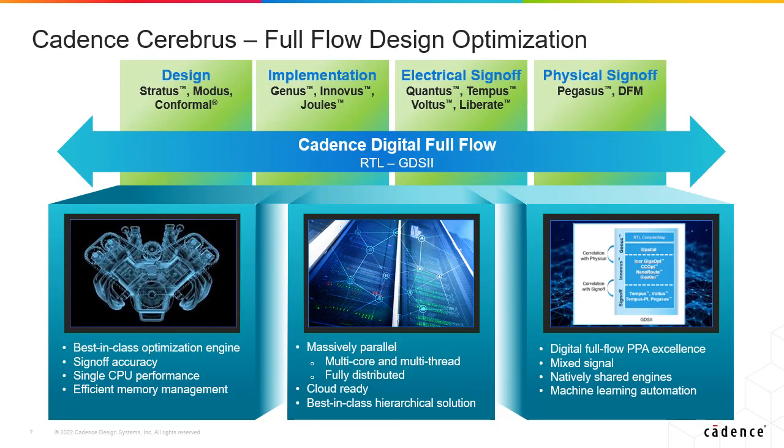The digital design has multiple levels of abstraction and typically starts with a high-level description of what it's supposed to do, written in either SystemC or SystemVerilog. This is then compiled using a high-level synthesis tool like Stratus, where all the architectural decisions and optimizations are made. At this stage, the designer has to plan for testability by inserting DFT through Modus.